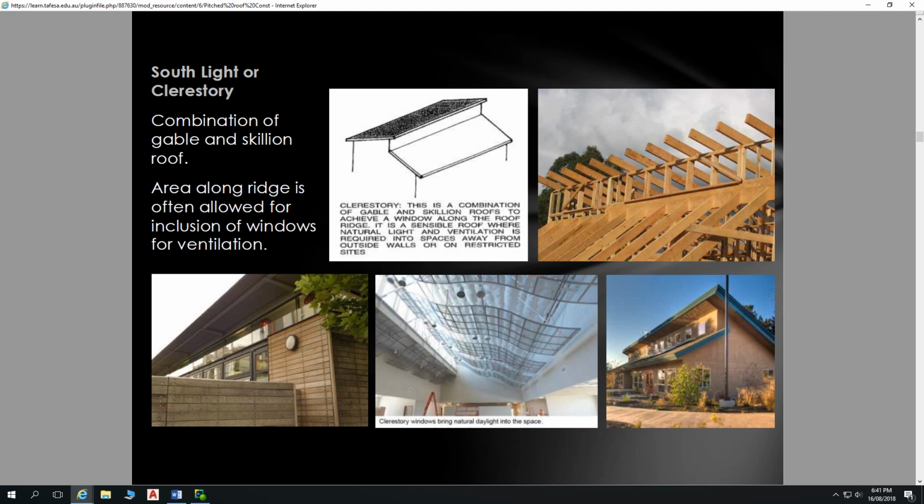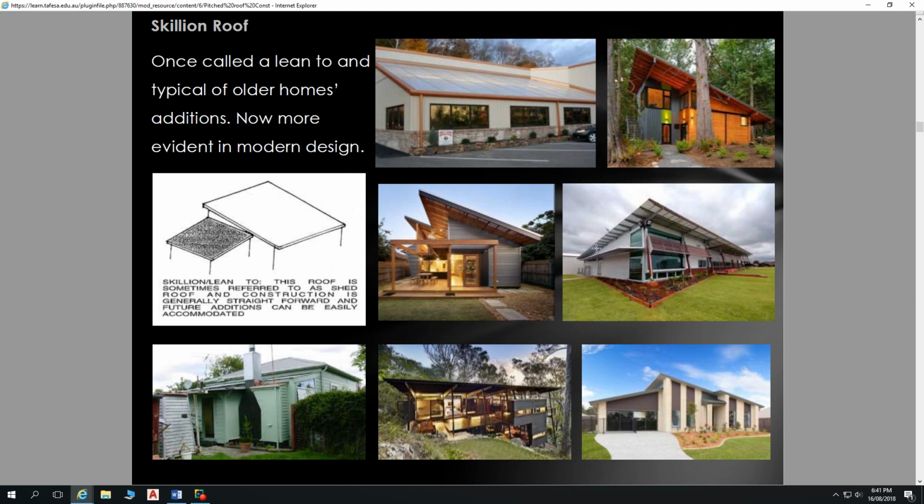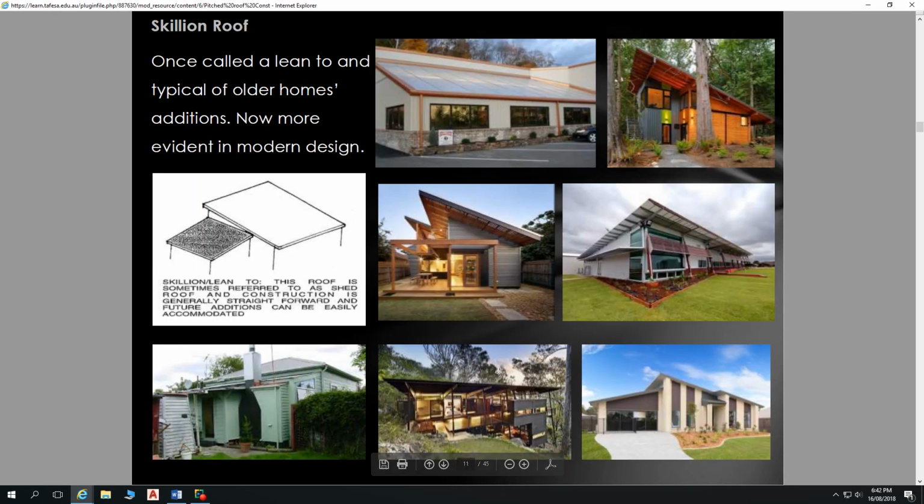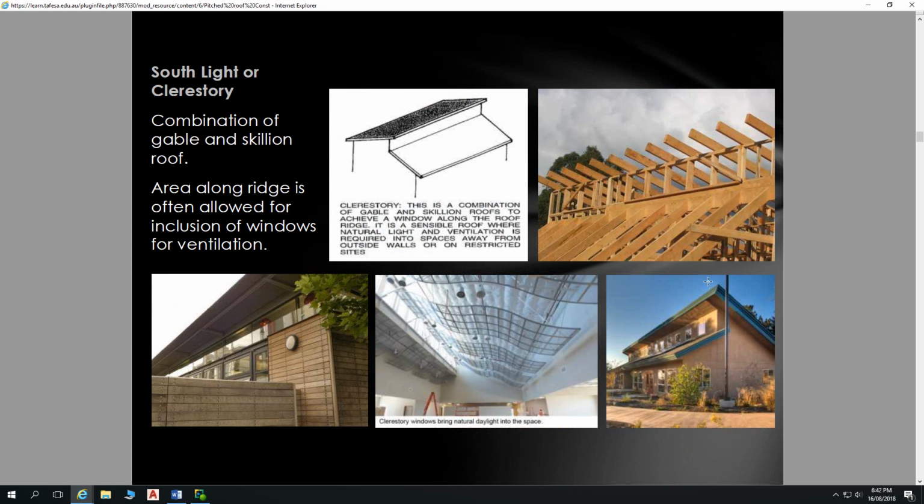I think it's a fantastic design approach. It doesn't quite meet the modern aesthetics of some of your other skillion roofs, and your very simplistic minimalist gable type structures, but certainly works very well in a functional sense for that comfort. There are issues around this though with building such structures in bushfire prone areas, in that debris etc. can gather in these areas near these windows, so you can be accumulating a fire source close to an opening in the building.